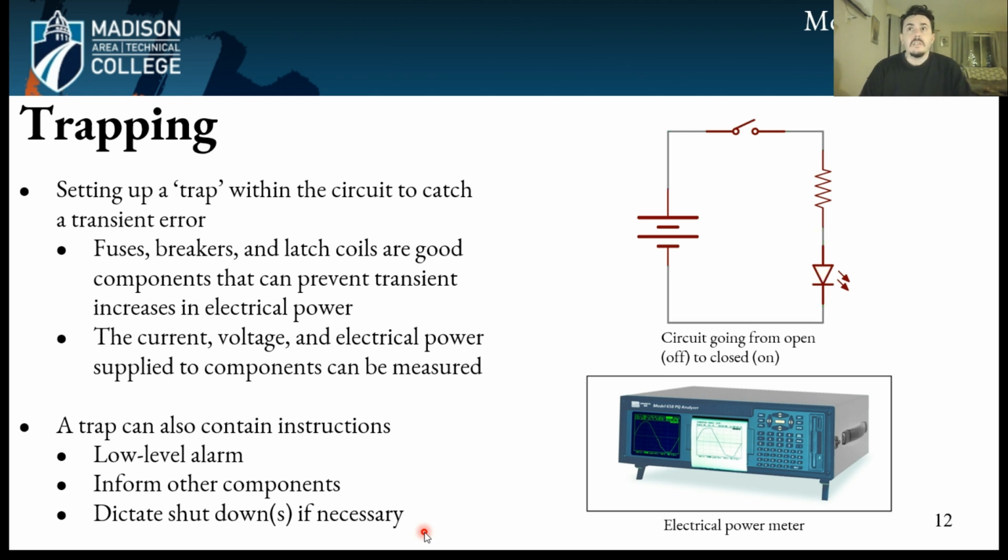So if this is something that is a failsafe, or kind of like an e-stop almost, you can tell the system to shut down. So if you detect a signal strong enough, or a signal above a certain value, you can say, okay, I need to shut this down. I need to shut down my pump. I need to shut down the valve. I need to stop running the software because there's an error that's just going to propagate and make everything worse.